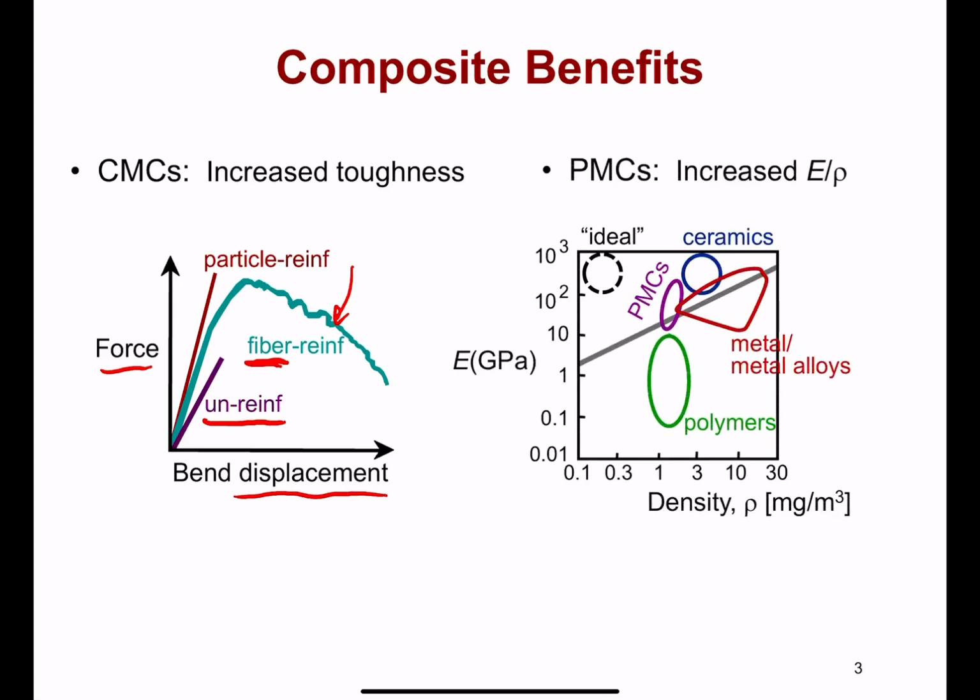Okay, over in polymer matrix composites, some of the triumphs there are showcased best in a modulus versus density plot, where, as you might predict, the ideal territory to be in this space, given the dimensions on the graph, would be to be at very low density values for material, but to be high in stiffness.